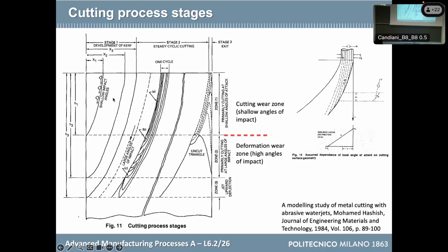When we go to x2, you see that the cutting front, because that curved line is a cutting front, you have to imagine the jet that is doing something like this, like it is represented here. And so the jet is exiting, but you see that the angle of exit tends to become more and more horizontal. So the jet is exiting quite horizontally there, because it is losing cutting power, and so it cannot dig anymore into the depth. But since there is a certain flow rate, that flow rate must be discharged somehow. And so it is moving like that, with that angle.